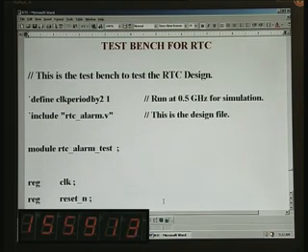See, for example, you want to push a button, what do you expect out of it? If I push once, you should increment only once, not 100 times. Erratically it will behave. If you do not debounce, it will give multiple pulses, because you are counting the pulses applied, it will be erratic. You expect just one increment, 1 must go to 2, but you will be annoyed to see 1 going to 8, 10 like that. So that is the purpose of debouncing.